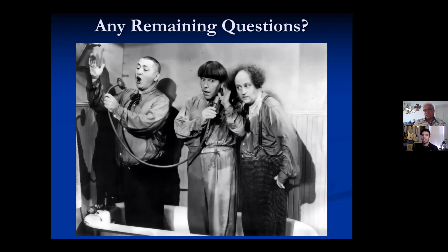One from John Erskine here is right hand versus left hand circular polarization. Where do you use? That's a really awesome question. I love it. So here's the difference. If you use a left-hand polarized helical, is what they are, not CPs, the RF will travel through the space like your left hand, right? If you're right-hand polarized, the RF travels through space right-handed.